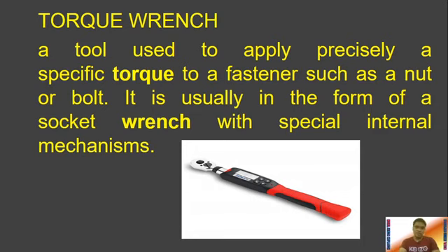This is important because if we over torque our bolt or nut, it will cause the bolt to lose its thread or to break. So we need to have a specific torque, and we can set that using our torque wrench. So that is to have a well torqued bolt. The torque is enough, not too much, and it is also not loosely torqued.